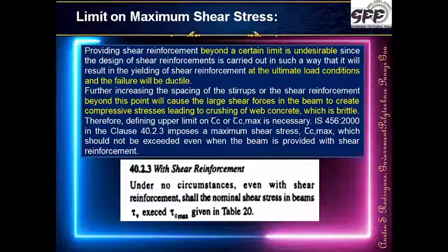Our designs are such that the steel yields, and because the steel yields, it gives us a warning, a caution. People and property can be moved to safety. Now suppose the area of steel is provided as shear reinforcement. If we go on increasing the amount of steel, then due to loading this steel will not yield, because it has not reached its yield point. The steel provided is obviously too much.